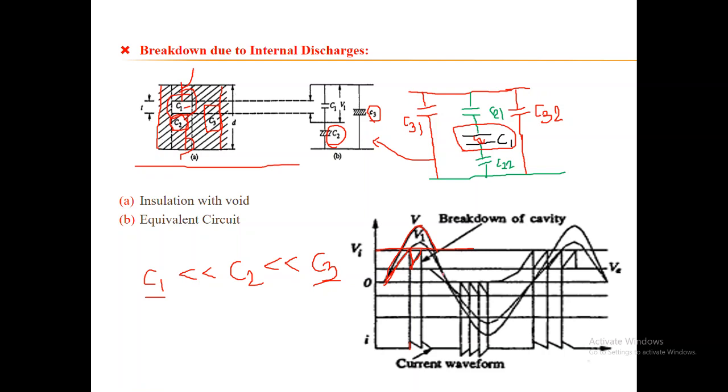As a result, no discharge is observed. As there is no discharge, the current is zero until the next discharge. Again the process is repeated in the negative half cycle as well. The capacitor will charge and discharge, charge and discharge. As a result, the current can also be observed, but with negative polarity. Okay, and the process is repeated.